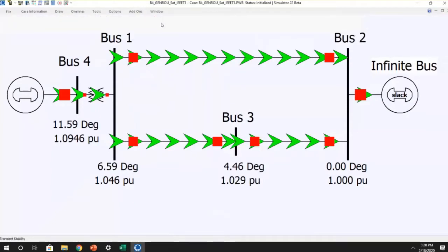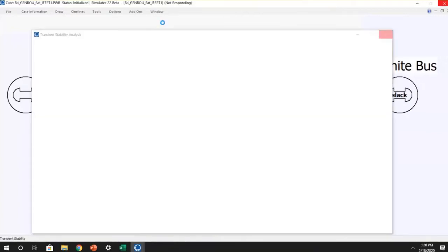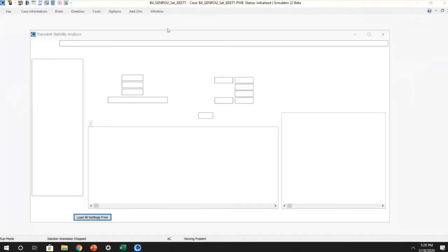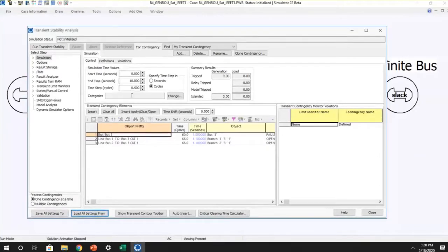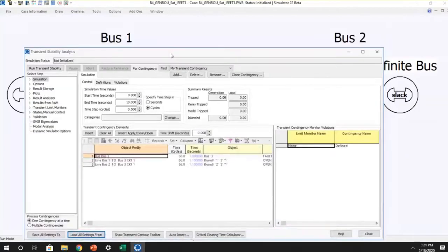Okay, so if we go to add on transient stability, where are the inputs for the under and over excitation limiters in that? The good thing about an IEEET1 is that it was before under and over excitation limiters, so those don't exist. Some models don't have them. So this is one that will let it just go really high. There's nothing going to limit it. It's just whatever the block diagram shows.